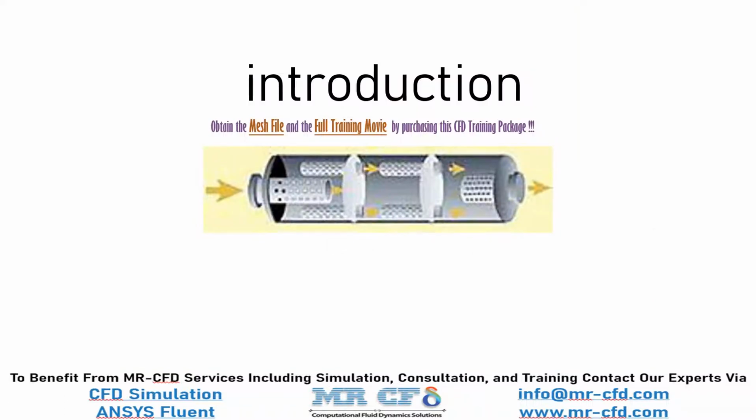A muffler or silencer is a device for reducing the noise emitted by a system. Mufflers are installed within the exhaust system of most internal combustion engines. The muffler is engineered as an acoustic device to reduce the loudness of the sound pressure created by the engine by acoustic quieting. The noise of the burning hot exhaust gas exiting the engine at high speed is abated by a series of passages and chambers lined with roving fiberglass insulation or resonating chambers harmonically tuned to cause destructive interference, wherein opposite sound waves cancel each other out.